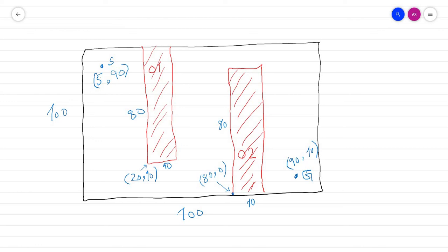You have to find a path that avoids the obstacles and reaches the goal using the RRT algorithm. After that you have to find a path using the RRT star algorithm. The only condition is that for the RRT star algorithm, the path should find the goal. The algorithm should not stop without finding the goal. For that you have to find the appropriate number of samples in the environment, and also adjust the values of R and EPS. You have to tell which value is better suited and gives you a better path.